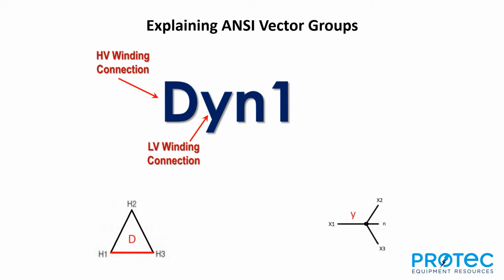We know because it's a Y that it has this neutral in the configuration, but we don't know that that neutral is brought to the outside of the transformer. So you'll see also a lowercase n right after the lowercase y. The lowercase n, we associate with the secondary or the Y transformer winding. And what that says is that that neutral that exists in the Y has been brought to the outside of the transformer, and we actually have access to connect to it.